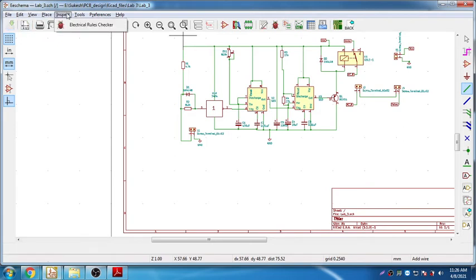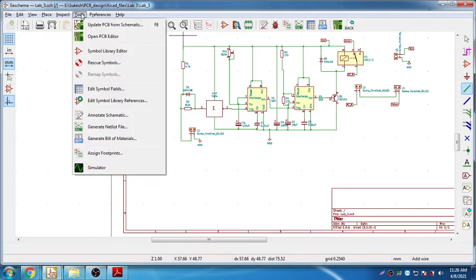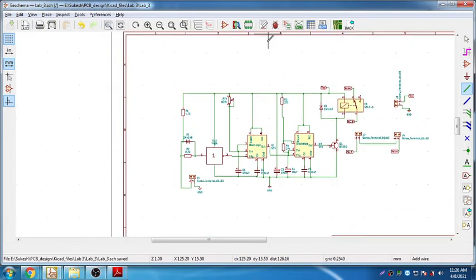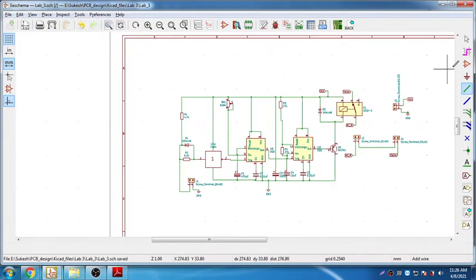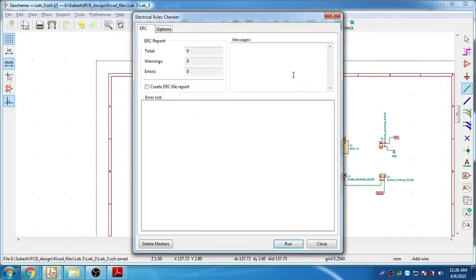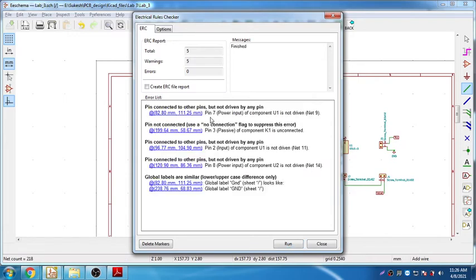Now I'm going to make, okay, footprint we need to assign. Okay, before footprint, let me just check for the design rule error if any. Okay, of course, I think we need to assign a power flag here to eliminate that. We'll see if it is required. Run. Okay, so not driven, that is a power, and this is actually pin not connected.